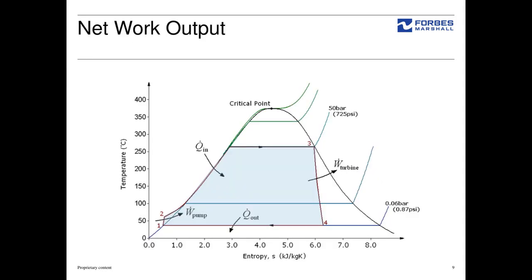As our Rankine cycle is used in power stations for generating power or work output, we want to make this process or cycle more and more efficient so that we can get a maximum work output through minimum heat input in your boiler. So what we can do, because we want to increase work output, is increase the area within these four processes.